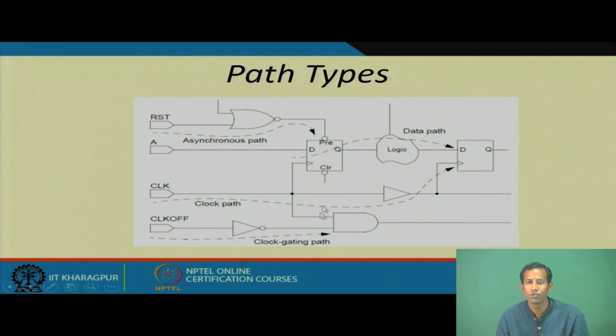So, to reduce this power, we use a technique: if I find any idle state in this particular condition, at that time the clock will be stopped. If it is in the running mode, or the wake mode, only at that time the clock will be activated and run continuously. So, to implement that type of logic, we need this clock gating path or clock gating circuit, which is useful for low power applications.